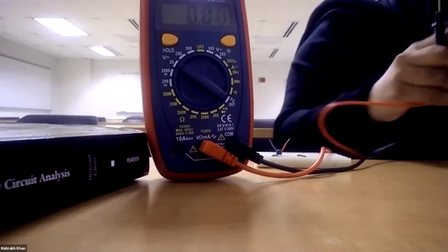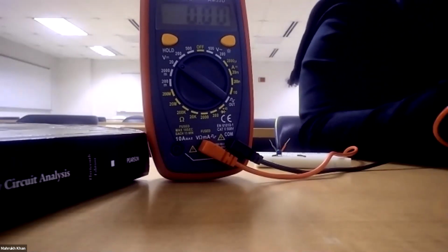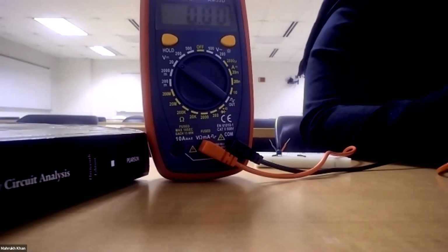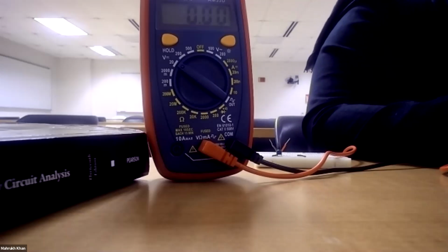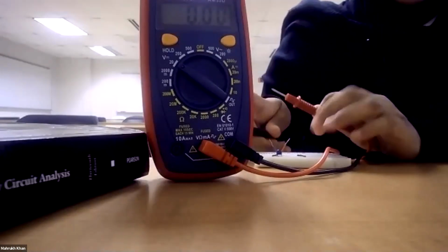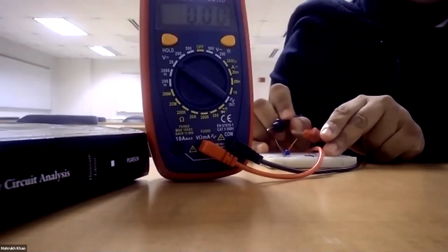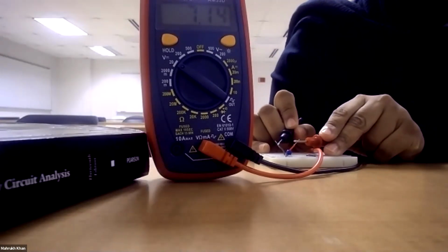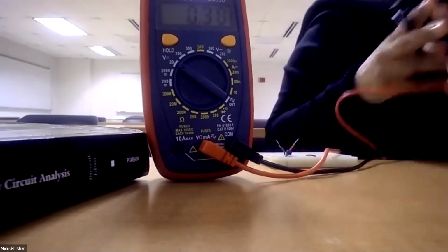Now, if the circuit is open, it will keep its charge. But if I want to discharge it quickly, what should I do? Connect a resistor to it. A small value of resistor, right? Let's check what voltage it has across it. It still has something like 7, right?